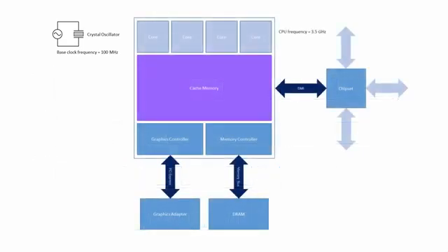A modern CPU might dynamically change its clock speed, depending on the task it's performing. For a demanding task, it can temporarily raise the clock frequency to get things done quicker. It can also throttle down the clock frequency if it starts getting too warm. A good cooling system will allow the CPU to operate at higher speeds for longer.